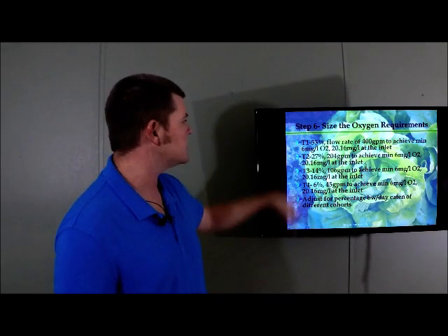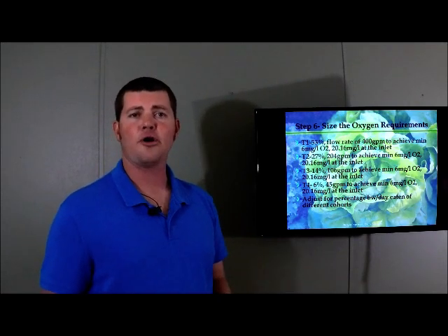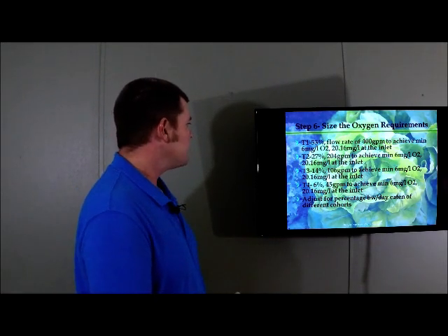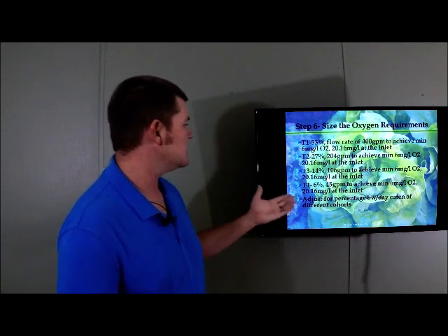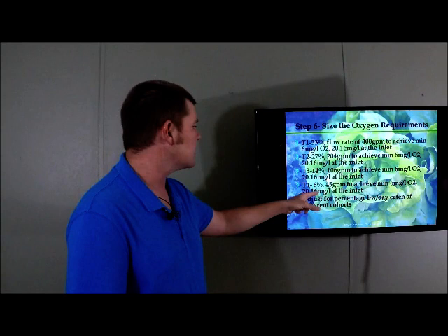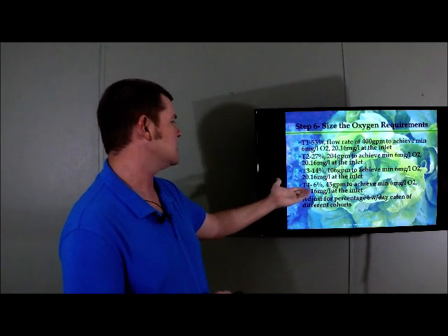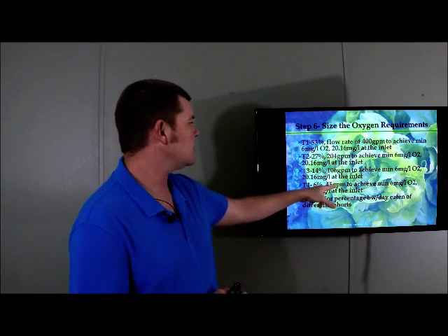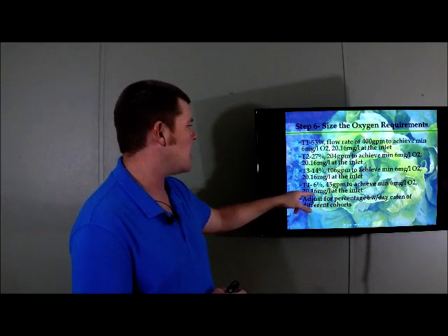So these are close numbers, but if you do the long math, you're going to get a harder number for each tank, okay? And the other way you can look at this is, if you didn't want to inject 20.16 milligrams per liter at the inlet and you wanted to inject less in this tank for some reason, you can increase the flow rate and inject less oxygen.